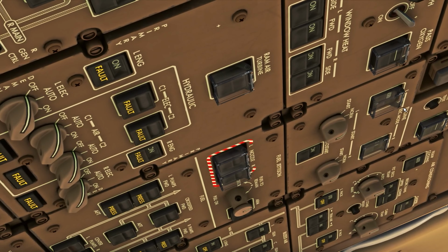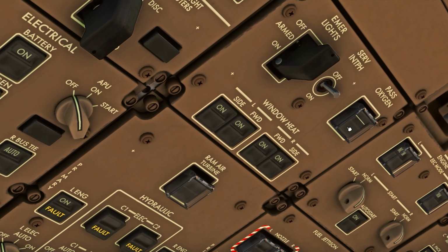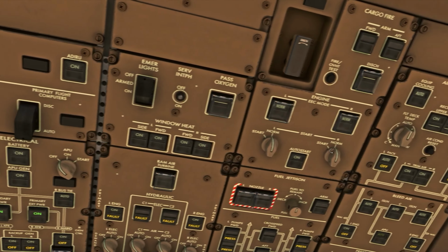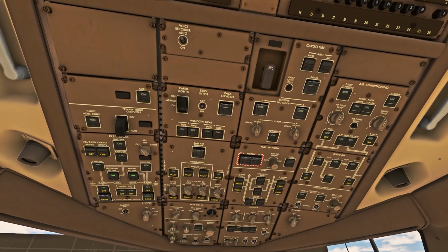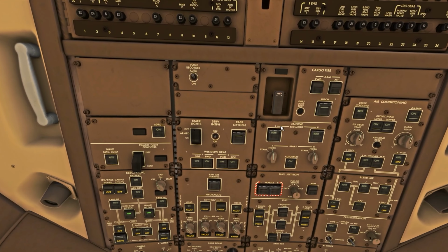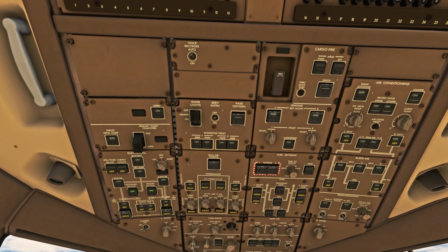We have our engine electrical mode. Let me get a better angle here, so you guys can see this whole panel. So you've got the engine mode, which we're going to leave in normal and guard it. These are the start switches and the auto start. We're going to leave auto start on. That's on for normal operations, and we're going to leave the starters in norm for now.